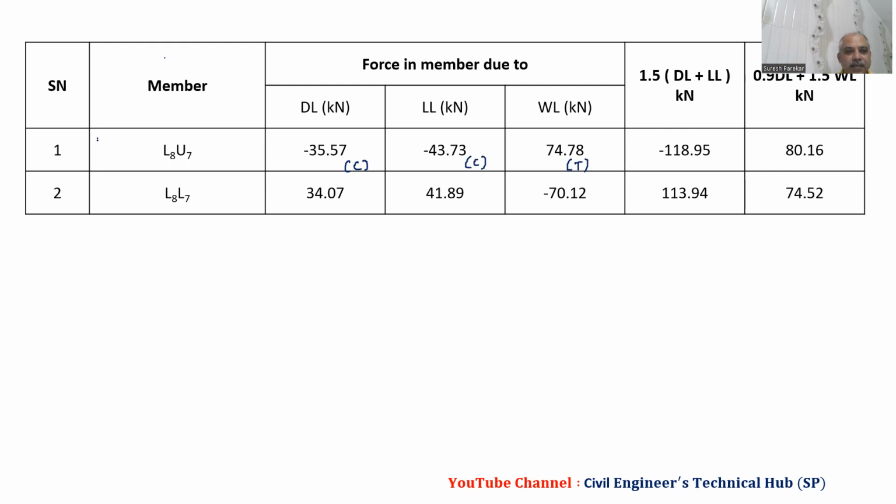This is actually the principal rafter. In the principal rafter we have compression due to dead and live load, and tension due to wind load. And this is the tie member, and in the tie member we have tension due to dead and live load and compression due to wind load. So we have 1.5 dead load plus wind load as minus, compression, and this is plus, so we have tension. Then we have these two, again plus, so tension, and this should be minus, so we have compression.